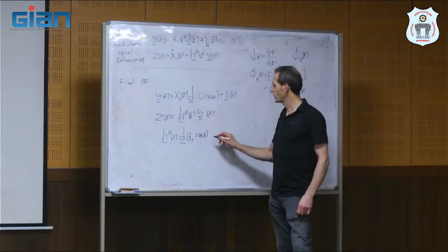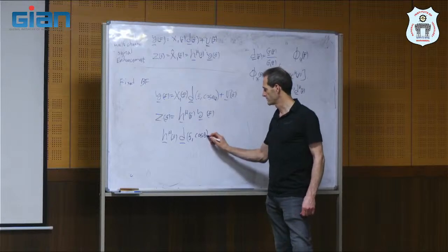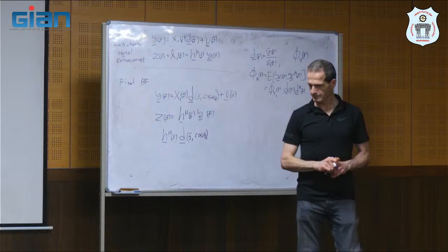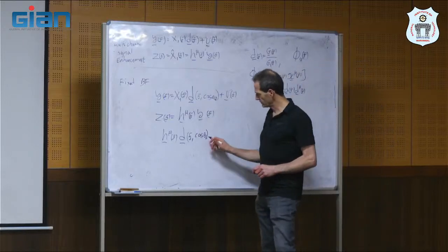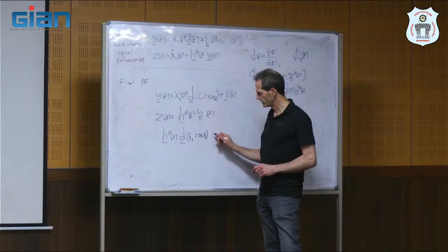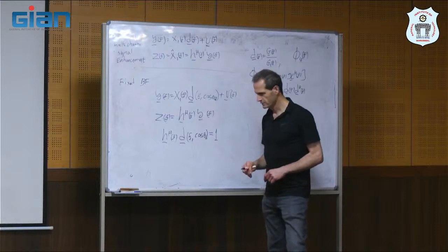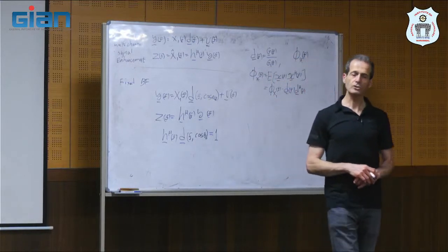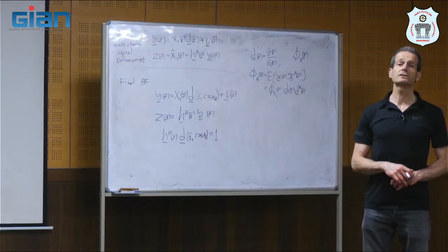Theta 0, let's call it theta 0, okay? Theta D, theta desired. From a certain direction, theta D. Now, in order that a signal that comes from this direction will not be distorted, I will require that this is 1. It's constant for all frequencies. So it's a distortionless constraint for a certain direction.